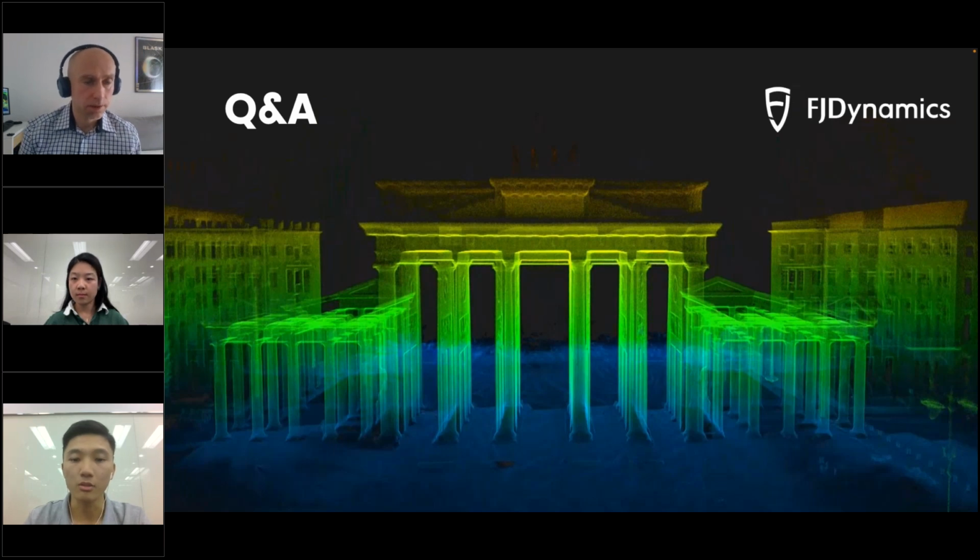I am an engineer surveyor, so I am used to the total station, but you can also use an RTK rover. And if the project does not demand very high accuracy, like tree scanning, forestry scanning, you can use the scanner without control points, without a total station, of course.